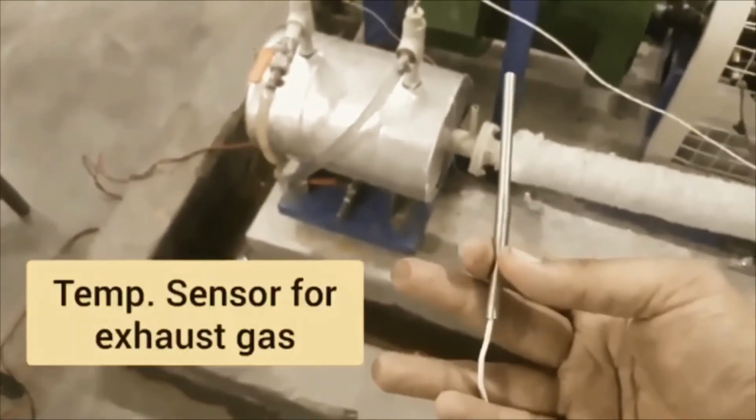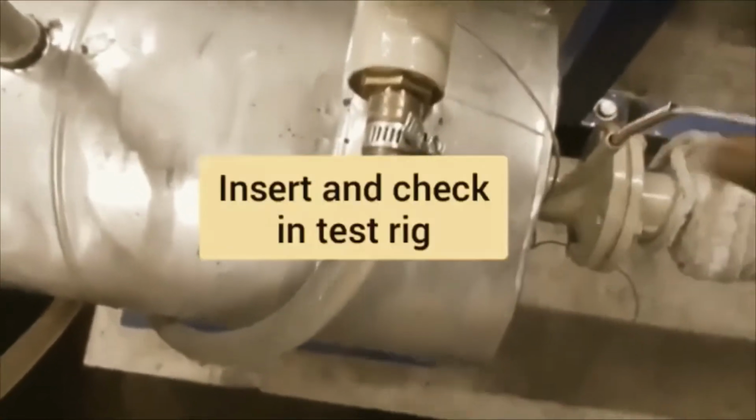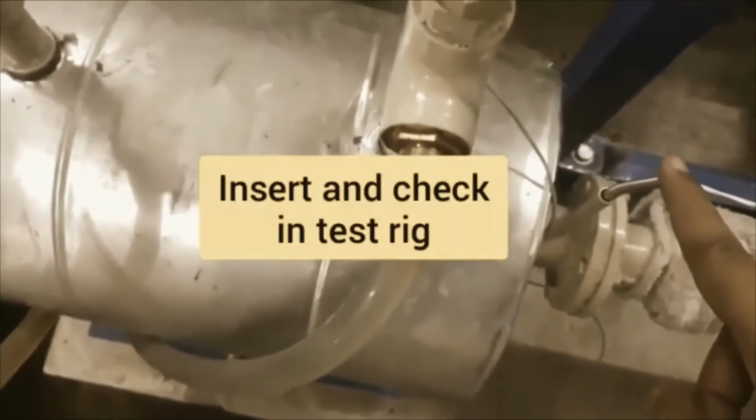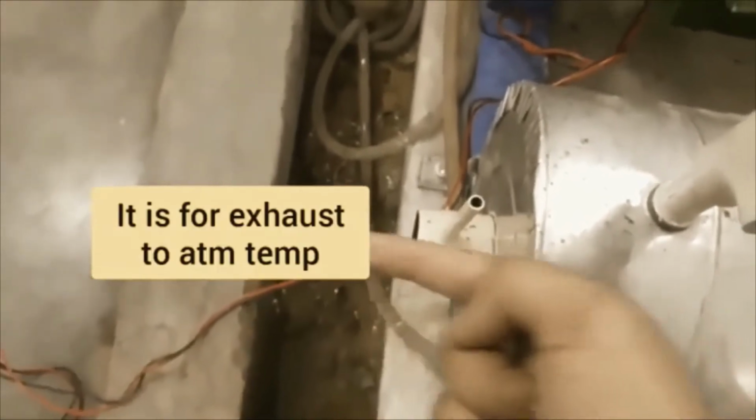For measuring the exhaust gas temperature, we use the temperature sensor. This sensor is used for the inlet and outlet temperature of the exhaust gas. Here is the inlet temperature into the calorimeter. All the temperature sensors here are K type. For the outlet condition, this is the way the exhaust gas is removed from the test engine.